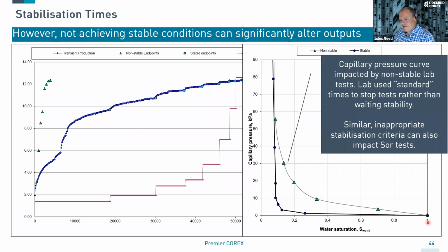this wasn't zero, that zero was actually down here. What you have is an area here that remains a water saturation of 1, and this would be entry pressure. And below this, you wouldn't expect any hydrocarbons. If you have that, that's the oil water contact. And if this was a different curve where this was the real zero point of capillary pressure, this here would be the free water level. So the point of zero is the free water level. And then this, where this begins to reduce, is entry pressure.